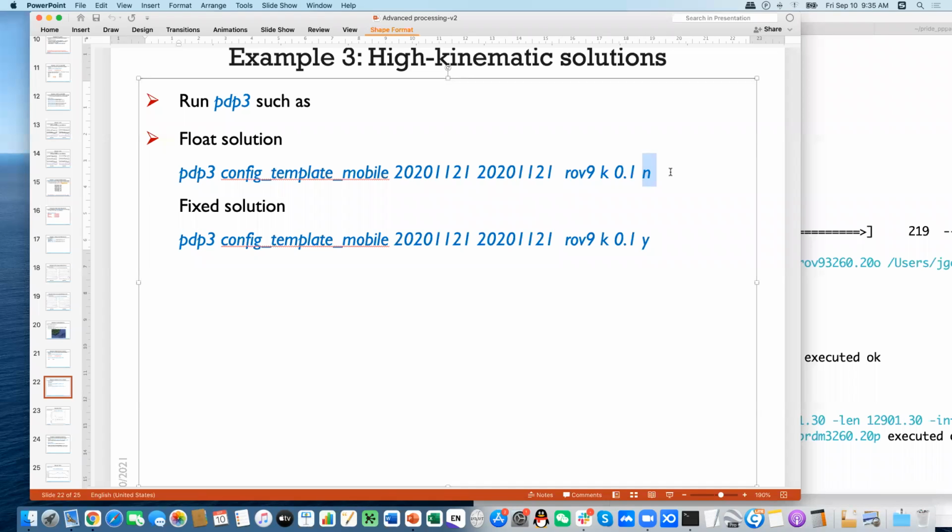If you have an inertial navigation system, you can record the attitude changes of your antenna and apply this correction to augment the GNSS data processing, but this can be very complicated. If you don't have an inertial navigation system, the shaking of the antenna cannot be recorded.